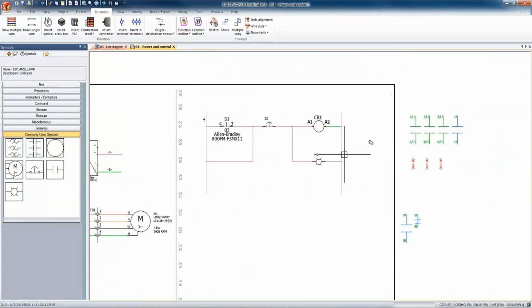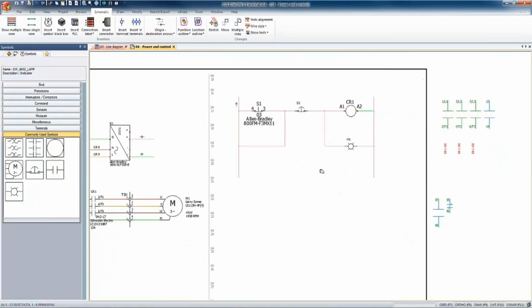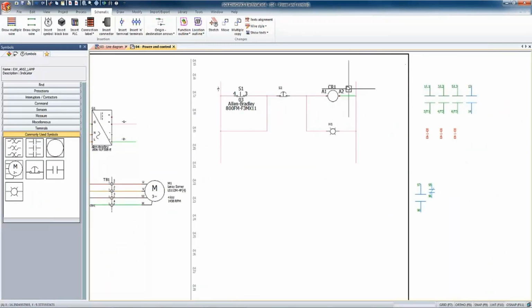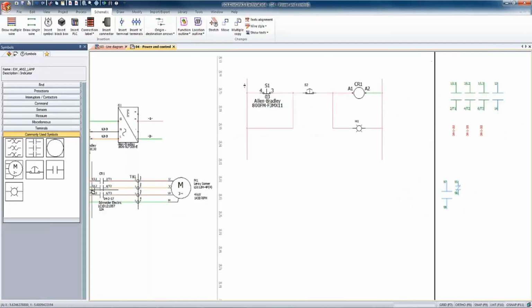And as we go forward, we can see here that we are maybe missing some component from the contactor. This contactor has a coil that needs to be attached. And SOLIDWORKS Electrical shows us that this is green, which means that it's connected to something. But what about the blue color? So there is no reference for the 13 and 14 points.